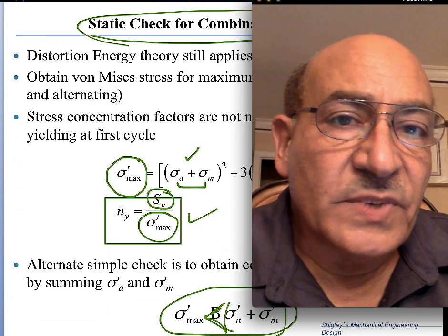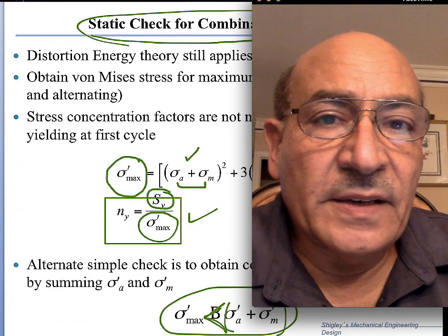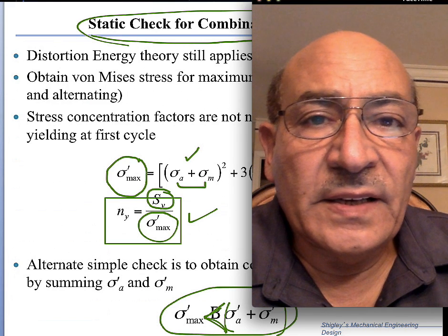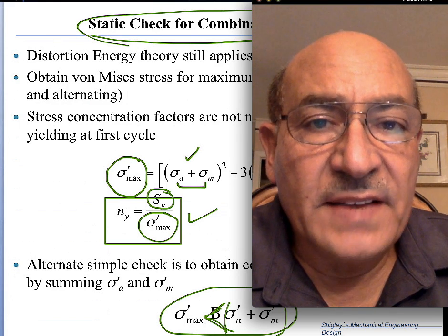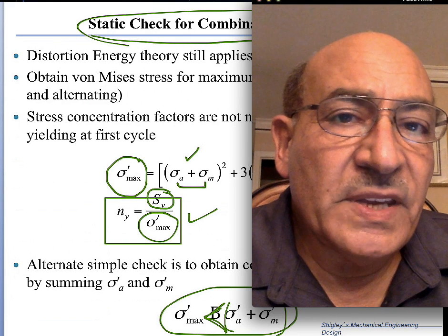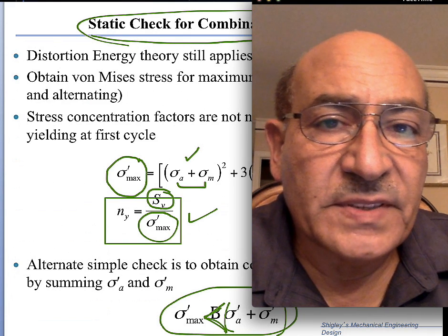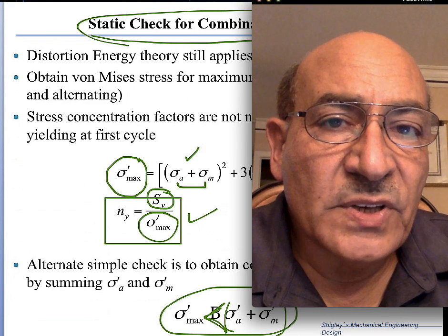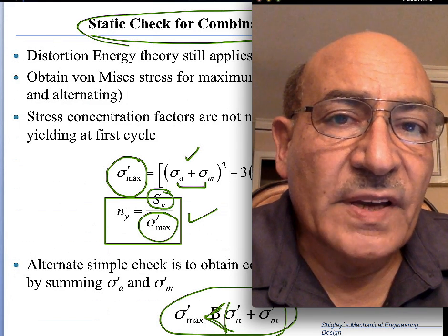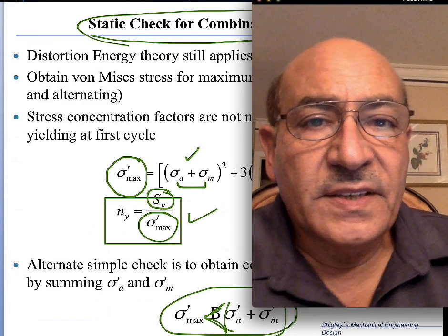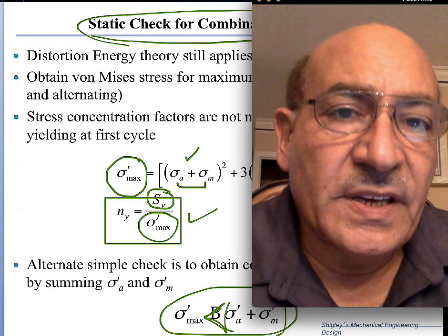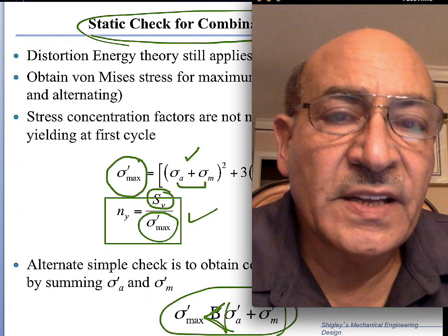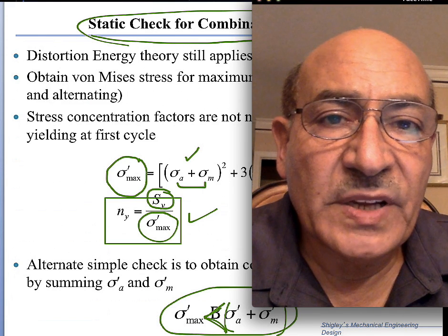In case we look for the alternating stress, we would use a load factor for the alternating axial stress, and for the mean we just use straightforward mean values for each of the components that go into the equivalent stress. Then we can follow a procedure similar to what we've done for just a single component of loading.